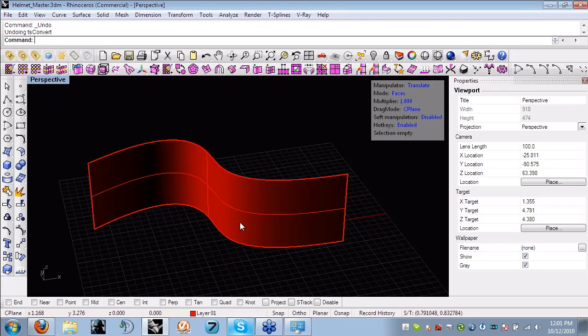If it's trimmed, and that's probably what a decent amount of your finished rings will be, you'll just lose the trimming information. So I think usually the best strategy is to just start with T-splines. We have done a few webinars showing how you can start with a trimmed model, modify it, and retrim it again. But I think T-splines is mainly used at the start of the process.